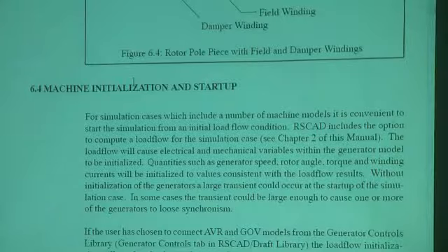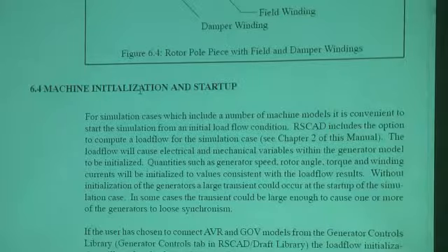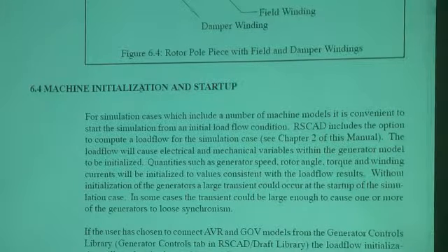What also happens with the load flow is it calculates all of the different parameters that need to be set inside the generator controls and sets up the controls so that the generator starts up stable.